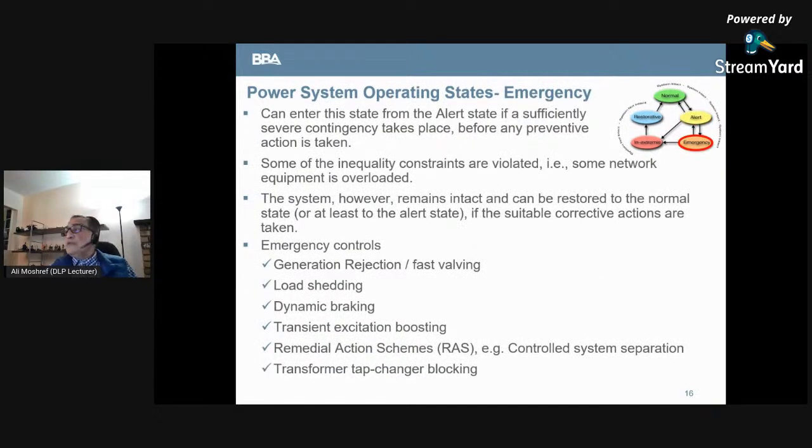So it goes through different actions. You can see that at the point that I go to an emergency situation, unfortunately, I sometimes have to do load shedding, right? I'm not reading the slide because I do not like reading slides. I'm just pointing to some important items in the slides. So when, for example, I see the voltages are low, I don't have reserve anymore, right? All my generators are online. I cannot get help anymore.